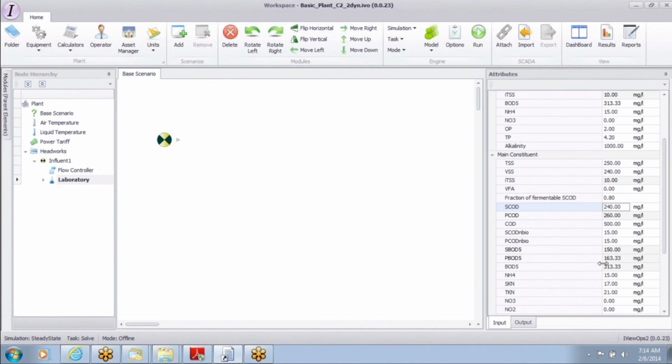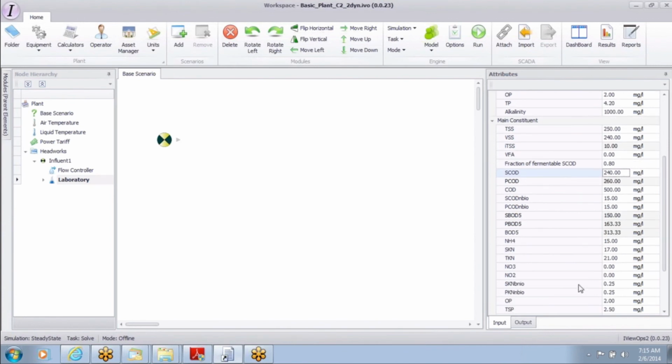Now, the BOD is actually computed internally, and I need to take you to the section which will compute this BOD based on a coefficient we put in. But let's finish the rest of the influent and we will come back to the BOD part. Now, what has happened to a few users is they know that their ammonia for this plant is 30. Now, the TKN over here, sitting over here, is 21.